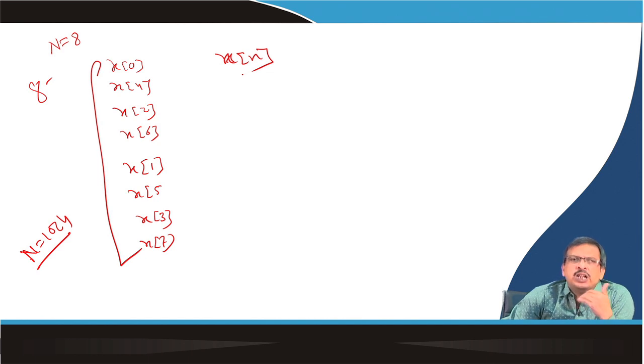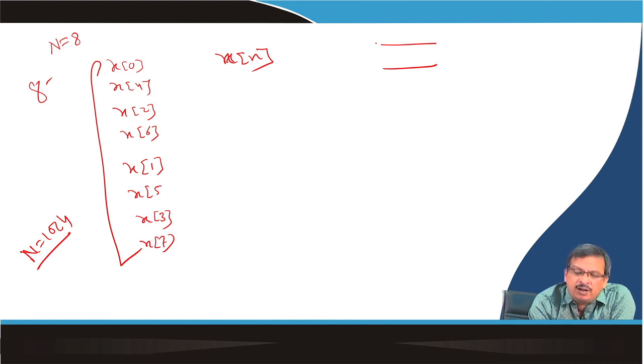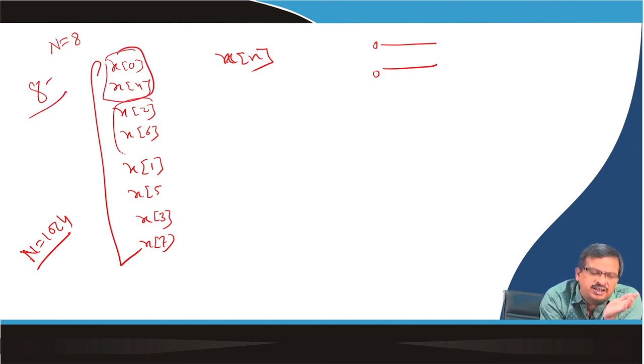When I want to implement the FFT algorithm, I know I have to implement the butterfly, and for each butterfly I require input signals which are jumbled as odd and even. In the case of 8, I know this kind of jumble, this kind of decimation in time, is required.